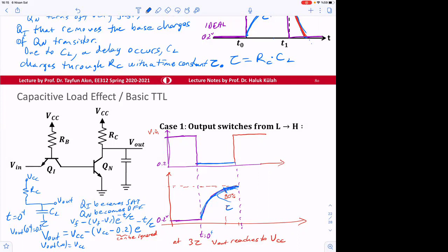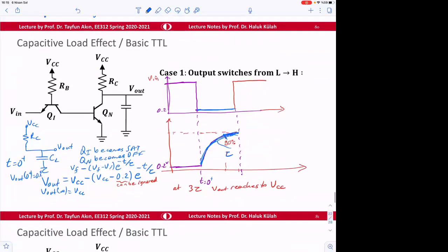In last year's exams, we asked you to determine the timing so that the maximum frequency of operation is determined. So you might want to define this one value, t, and then you can consider this as t divided by 2. And if it is a 50% duty cycle, this should be t divided by 2.